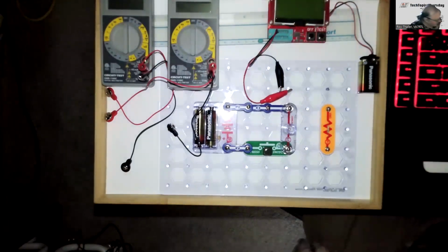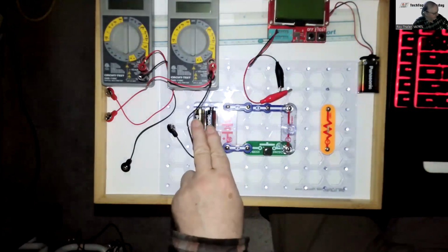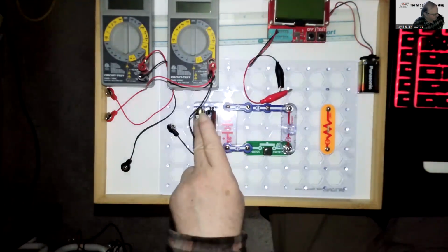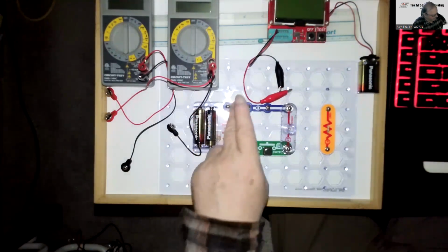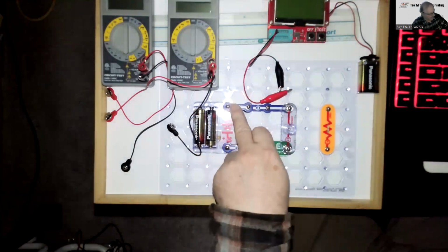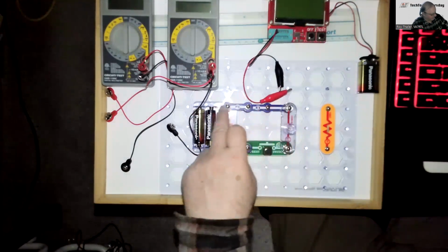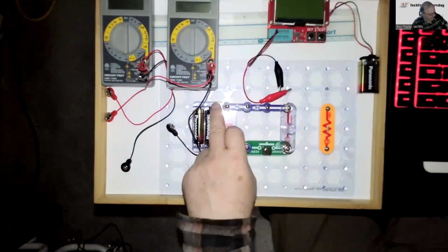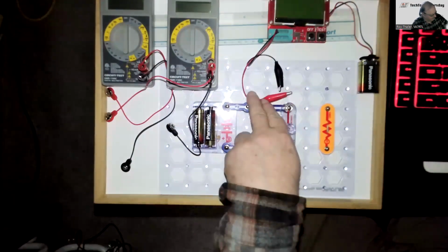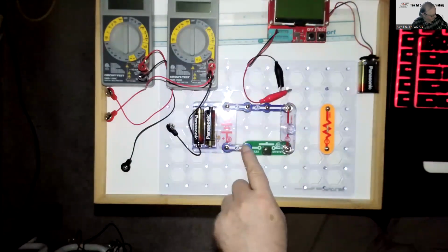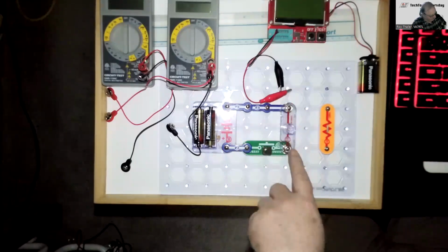And what we've got here is basically a battery. So it's two batteries in series. So it's 1.5 plus 1.5, which will give us 3 volts. This is the negative side of the battery, and this is typically the ground. So we typically try not to put any control or anything in the ground side of things, but it doesn't matter if the switch was here or if the switch was there. Then on this side, which is the positive side, we have a push button, and then we have a light.